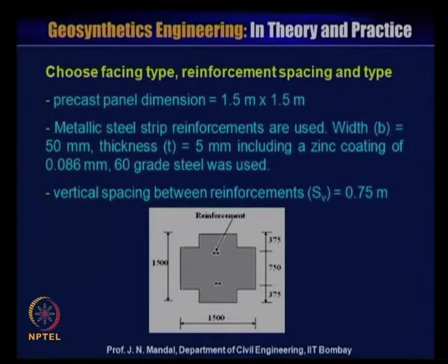And when you design this metallic reinforced soil retaining wall, you have to choose the facing element. There are different types of facing elements. I am just showing one cruciform facing element whose dimension is about 1.5 meter by 1.5 meter.